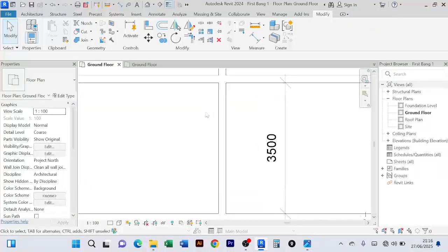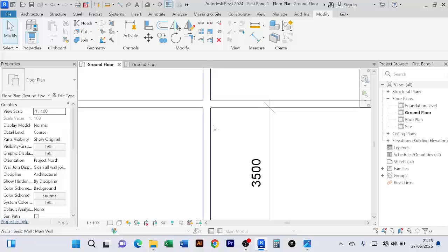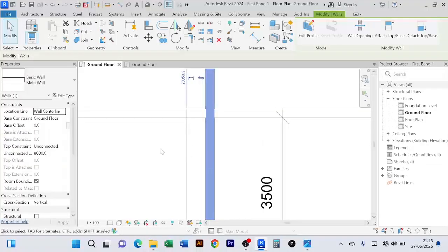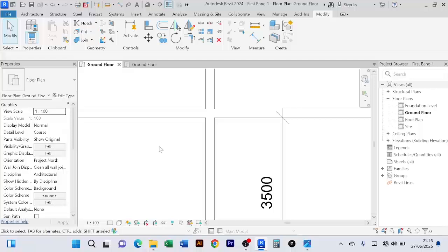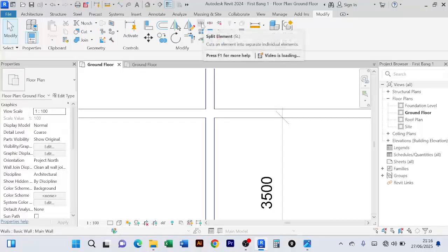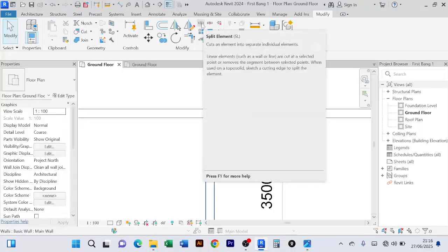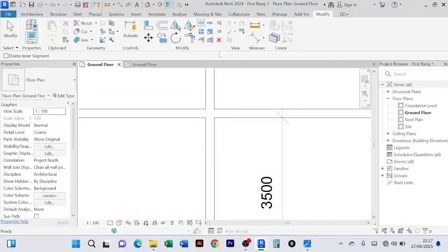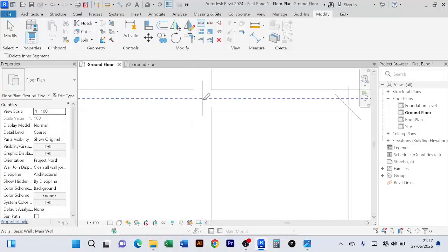So the trim to extend works at some point, but there are points where it cannot work, and all these ones do work at certain levels, and sometimes you may need to use a specific option to handle your situation. I can now split, just come here in the middle to show me that I'm splitting this wall.